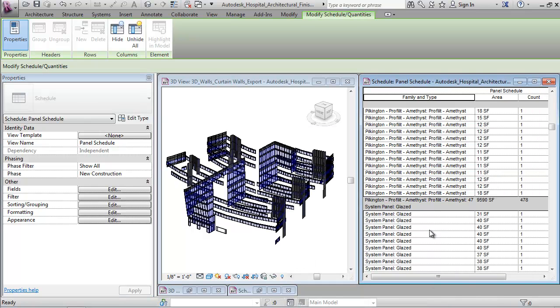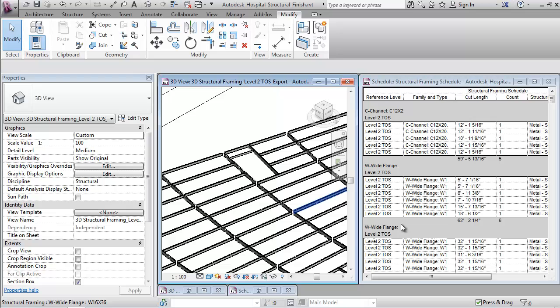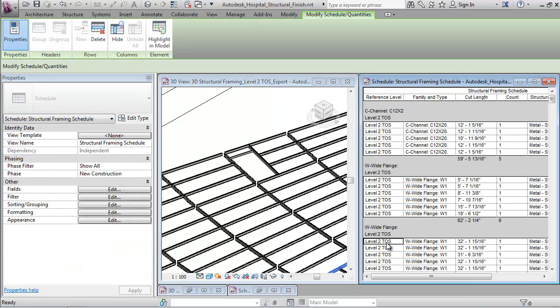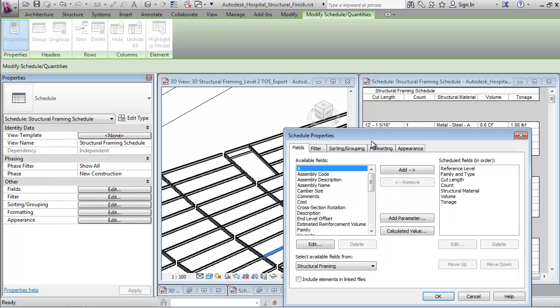Here we see how the Autodesk Construction Solution offers several ways to gain access to quantity information early in the process. By leveraging tools directly from within modeling applications, such as Autodesk Revit, we can quickly get a high level of understanding of the project costs. Schedules created by the designer can be leveraged by adding counts and totals, or a custom table can be generated on the fly to give you the feedback and quantities from the model information immediately.